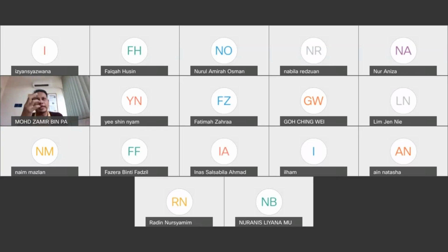So thermal cycle is actually a cycle of high temperature processes imposed to the silicon or to the substrate or to your IC during the whole cycle of processing from day 1 until day 60, for example, or day 90. So every single thermal processing that you use will actually cause some level of dopant redistribution.